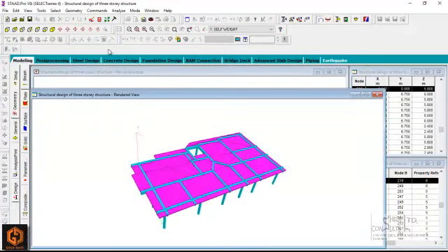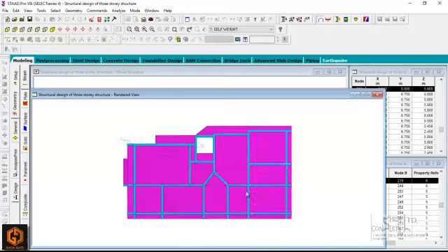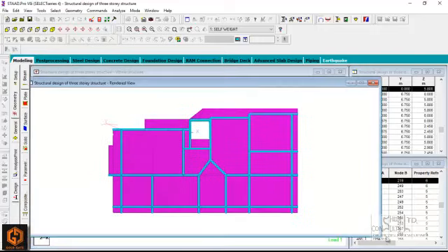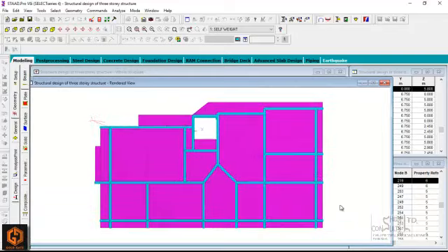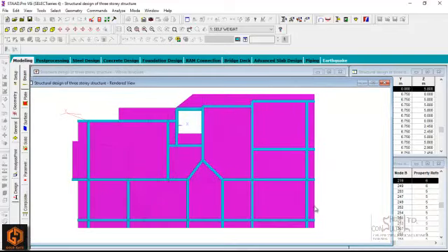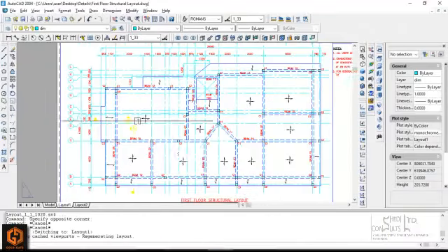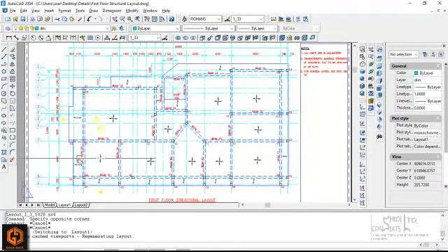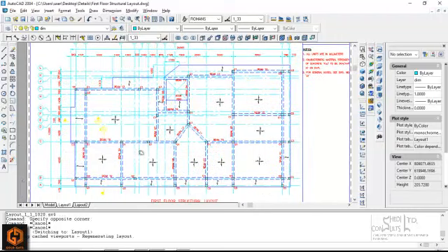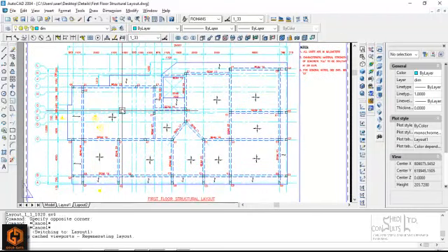So if you look at that, you have to ensure that the structural member orientation, stiffness modeling, member sizes, and isotropic properties as defined are correct in line with your drawing. Okay, so your members have to be correct, sizes have to be correct, lengthwise, member sizes. So if you look at that, we have that two-way panel, that cantilever there, cantilever here, cantilever all around the perimeter of the building.